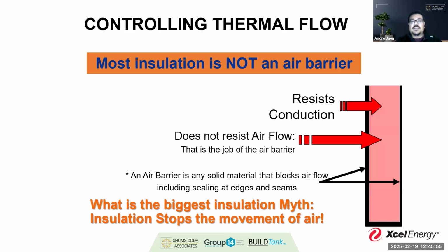So, what's the biggest insulation myth? That insulation stops the movement of air. No, it doesn't. Insulation does not stop airflow. Insulation likes to capture air, but that's it. It does not stop it. It can't resist wind washing.